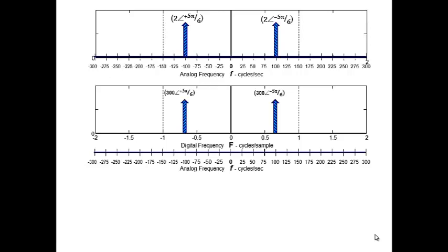And now we make copies of it, copies of that complete spectrum, where every copy is centered on an integer multiple of the sampling rate. So we pick up those, make a copy, center them on capital F equals 1, and capital F equals 2, and capital F equals 3. And make copies and go in the negative way too, centered on -1, and -2, and -3. And I'm going to turn off the lights and help you read some of the fuzzy things up there, because it's kind of important, the fine print.